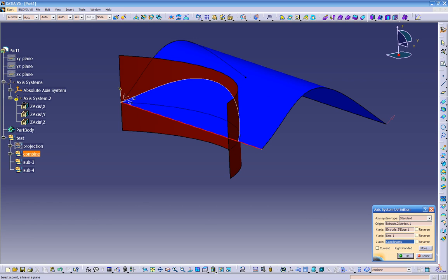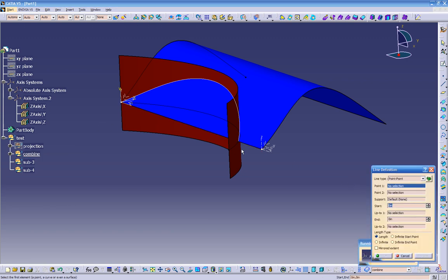The reason we didn't see the line right now is because it didn't like something about it. So we can put no selection, and you can create your line. The reason that we get that little error over here is because when I click on this point, it is the point of the axis. So we don't want to use this axis as a point.